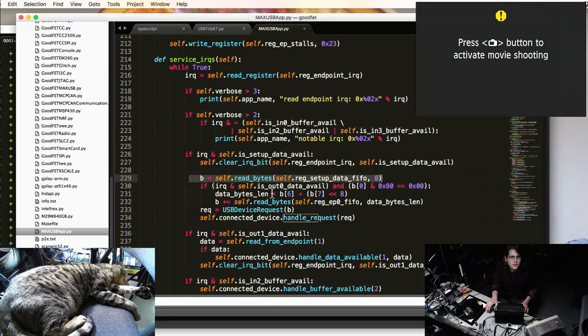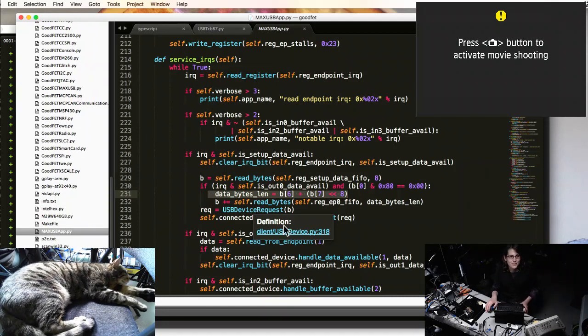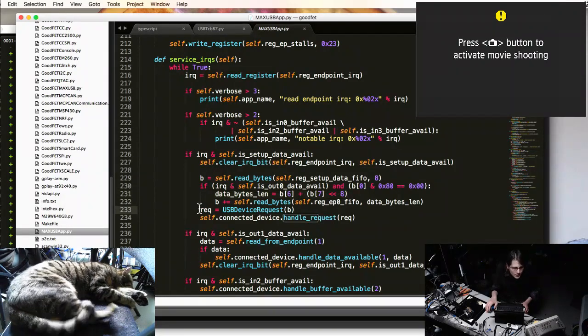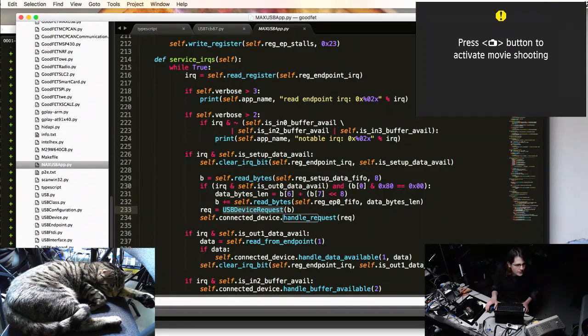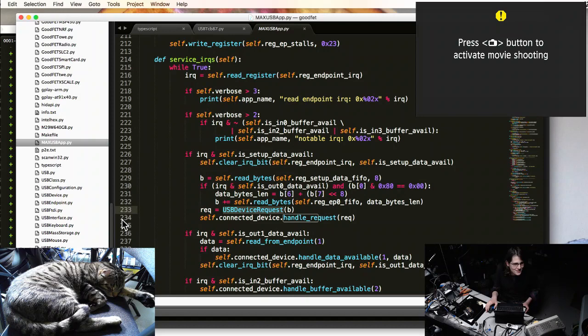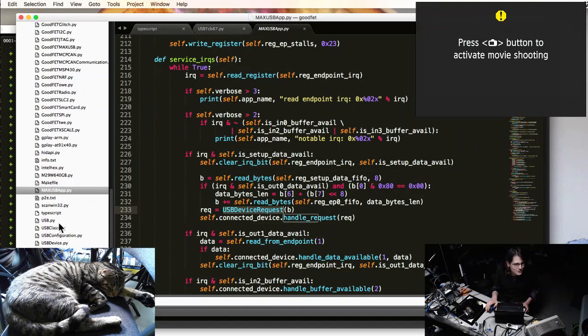And this is a little non-obvious, but this is reading the length field from that setup packet. A lot of documentation calls it wLength because it has a kind of Hungarian notation, the prefixes for the type of the variable. So I guess we just have to look up how to get this out of a USB device request. I guess this has been considered, even though I don't see any of the existing drivers here using it.